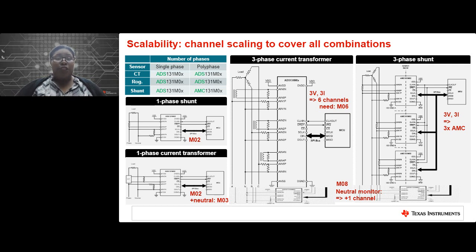architecture, which will reduce the amount of additional components needed for the customer when traditionally doing this type of architecture with the ADS131M0x. So because of the AMC131M0x, you will now be able to remove over 36 additional components that you would traditionally see without having this part, because of the fact that it's providing that data and power isolation.